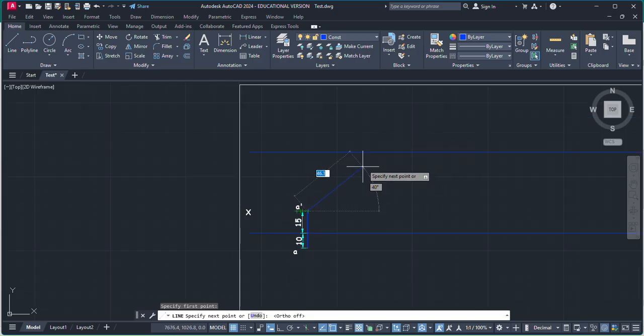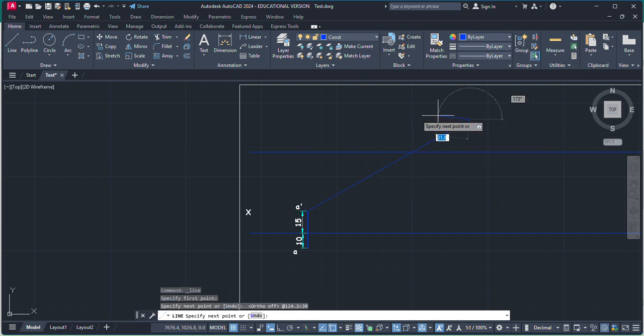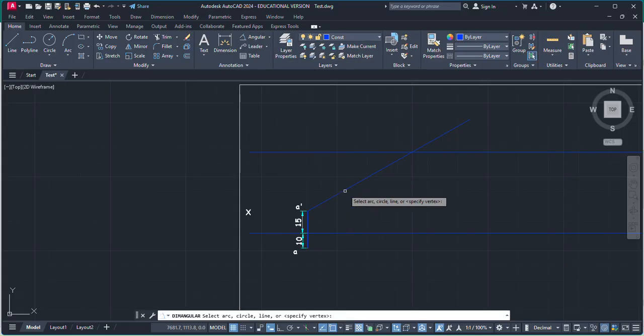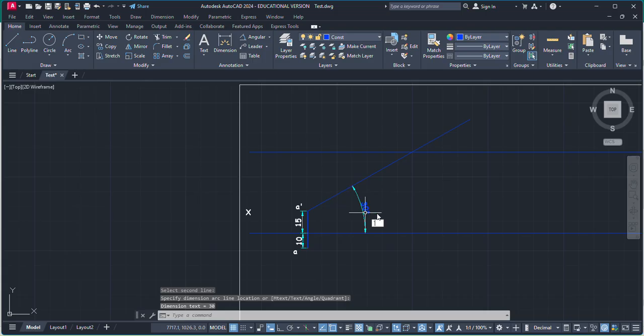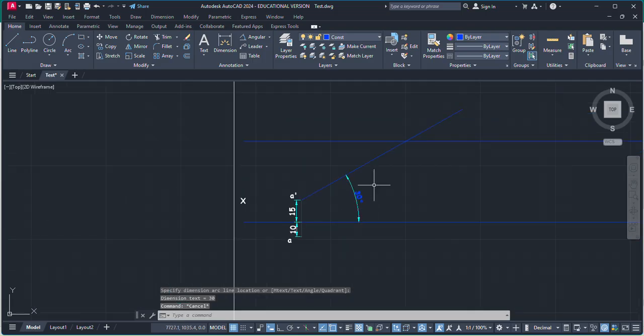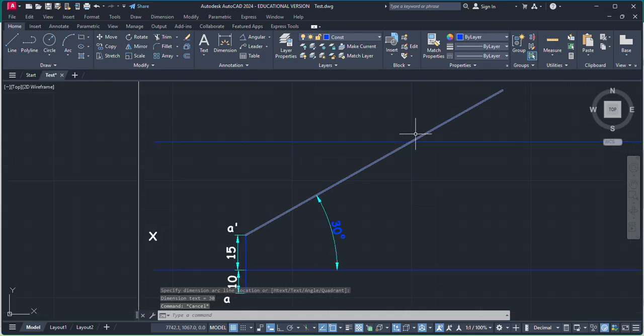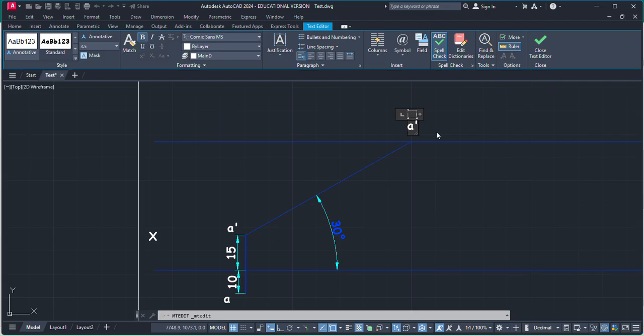So I'm just going to make it large enough so that it will intersect with this horizontal line, because we know the endpoint is somewhere there. Now you have to make sure this line is at an angle of 30 degrees. So keep this length as it is, press tab, and the angle should be 30 degrees. So now this line is inclined at 30 degrees with the HP, and we know the end is on this horizontal line. So this is the point of intersection. Just going to trim this. Now this is our endpoint for the true line, which is noted by B1 dash.